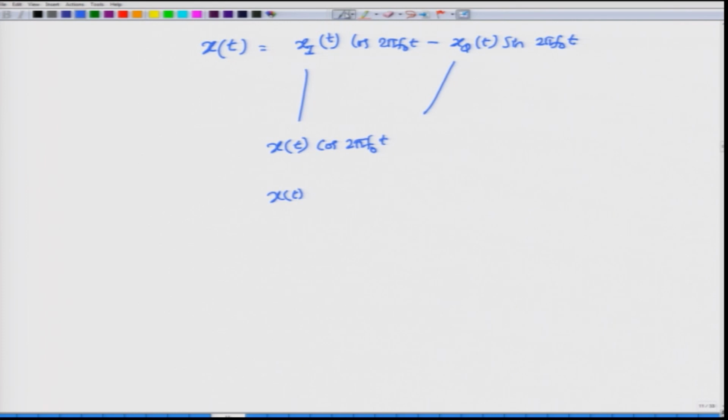So, what would that do? It would actually correlate these two and then extract out xi. The output would be proportional, not exactly equal, since its amplitude will be slightly different, but it is possible for you to actually extract these signals, as you can verify from your communication system textbooks.